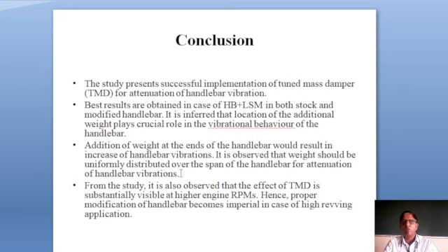Always distribute the mass over the span of the handlebar so that it is uniformly distributed, and the uniformly distributed weight has shown results that it is more effective in vibration attenuation.